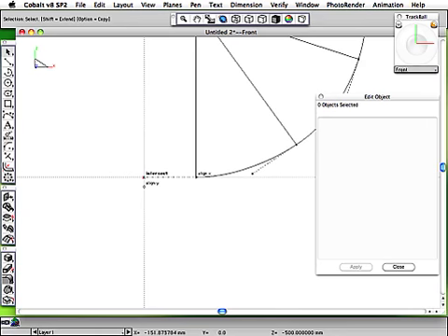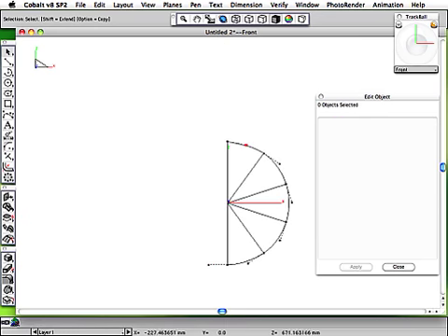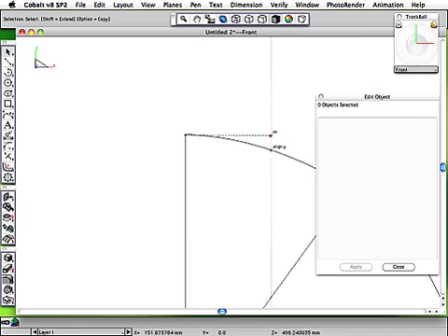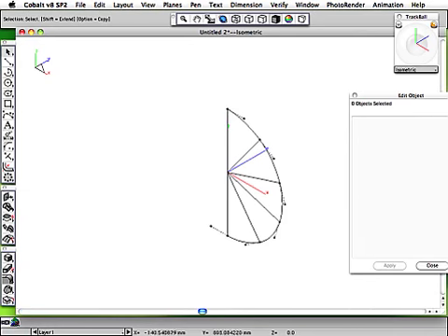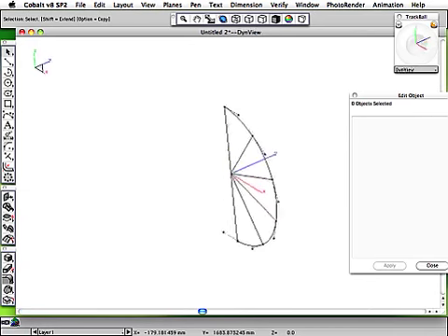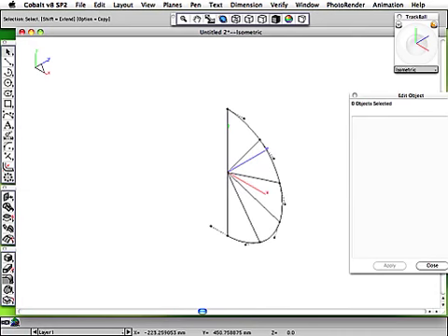Now if I zoom in here, I'll grab this handle on the end of the curve and pull it horizontal. That now makes the end of that curve perpendicular to the axis, which is important if I'm going to mirror image this thing and expect it to be tangential across the join. So that's my curve running in one direction.